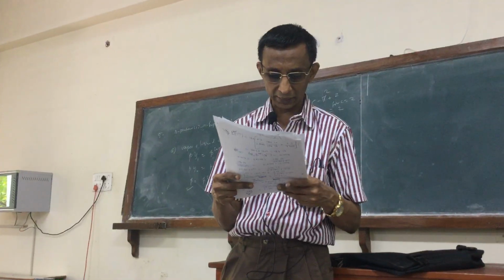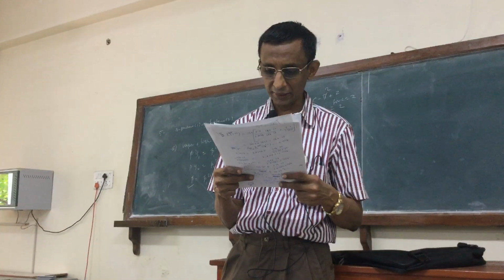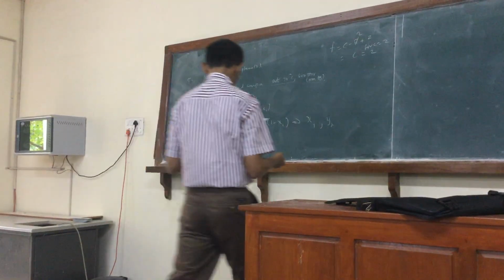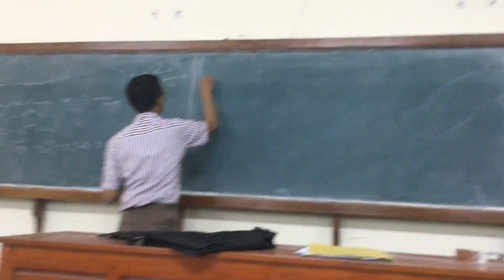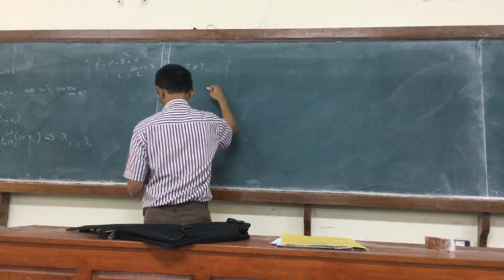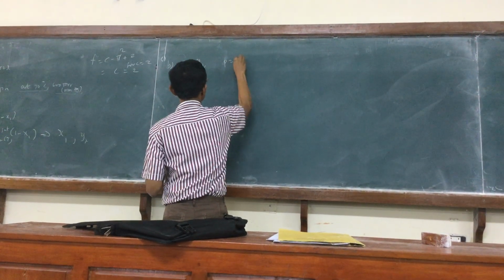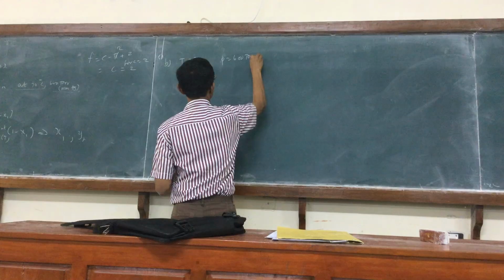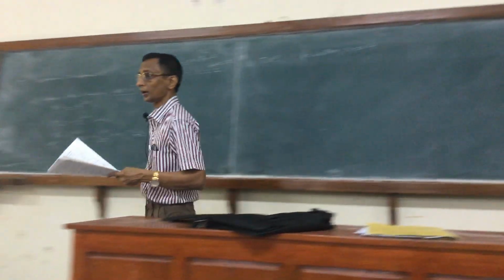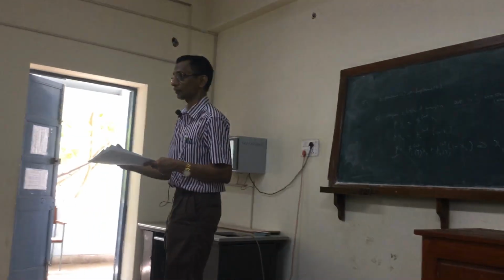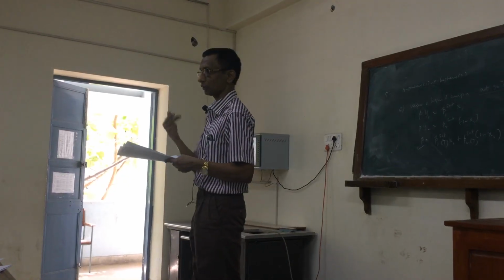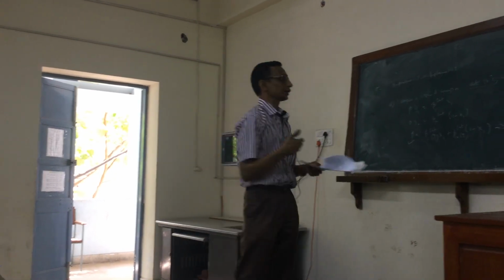Now let's take up the next one. Find T and y1 when P is equal to 600 torr and x1 is equal to 0.4. So this is clearly a bubble temperature calculation, which we saw even for the ideal case requires an iterative solution. So let's do one or two steps of the iteration.